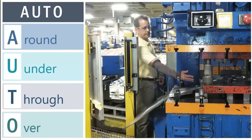The other concept that's important when you're auditing and looking at guards is: can you reach around, under, through, or over that guard? Again, this will come up in a few other ones. This is a press with a light curtain configuration, with a transmitter next to the character in the picture, out to a mirror across the front, to another mirror, back to a receiver on the other side of the press. Well, okay, that kind of sort of protects the front of the machine, but doesn't protect somebody from coming up on the side and reaching into the point of hazard. So we'll see around, under, through, and over.